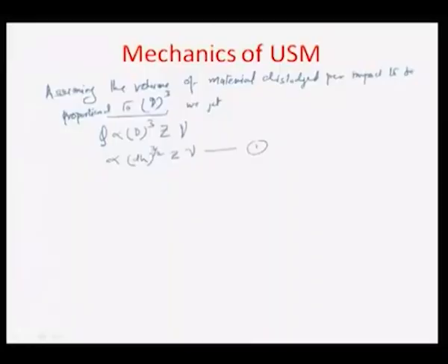Okay. It can be more than that, the impact force can be more than that per unit area, but at least it should be the flow stress of the material for the material to start coming out or start getting fractured. So, the assumption behind the model really is to somehow be able to predict from the applied force what amount of force per unit area is coming on one grain, as a matter of fact on many grains, and that has to be somehow equated to the ultimate flow stress of the material that you are removing from the surface. So, let us look at it and see what this estimate is.